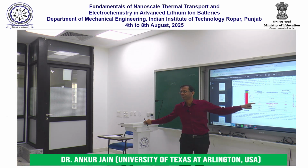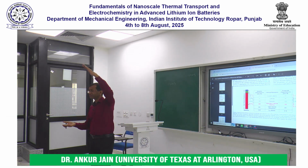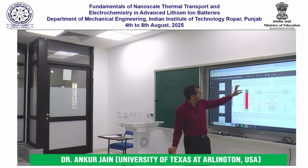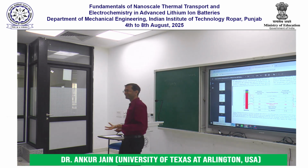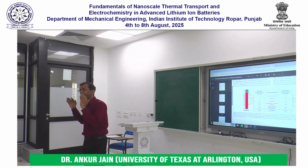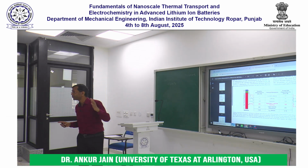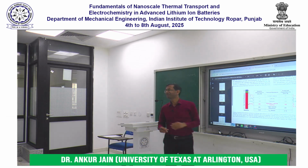Resistance 0, right? If you take a lot of effort, that resistance can be brought down all the way to 0. But even then, if this green thing becomes 0, the total thermal resistance still does not change much, right? You've got to put your efforts in the right place. And here, the thing that requires the most attention is the interface, not the material itself.